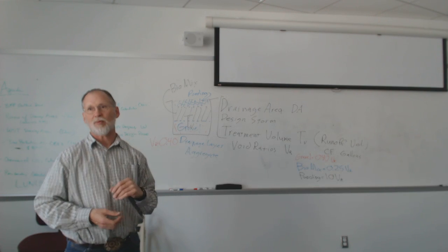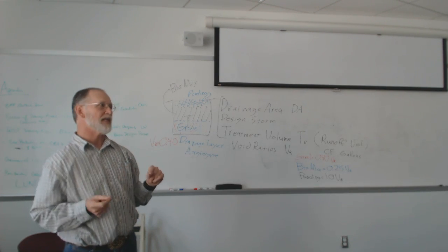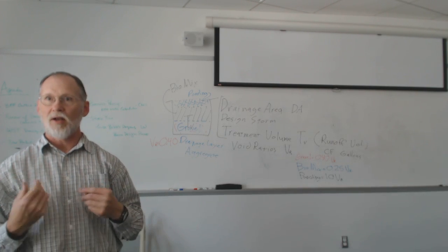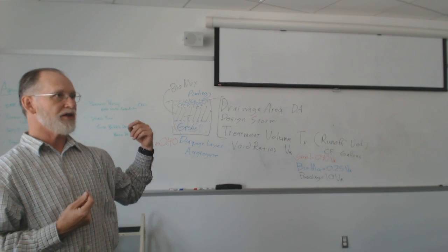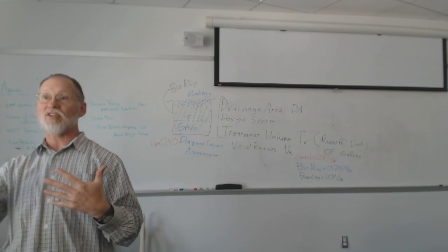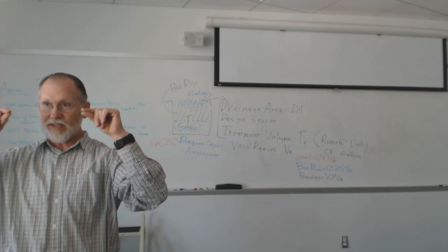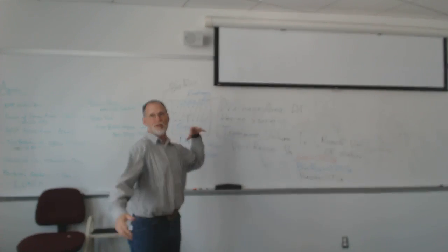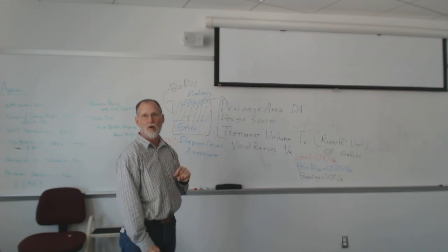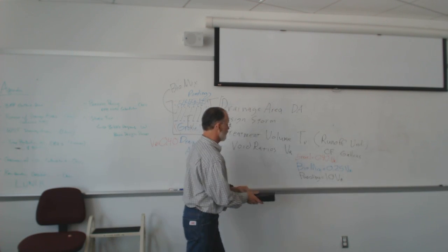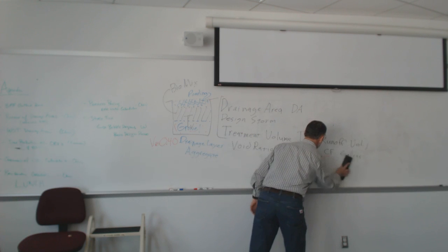These best management practices do very little for those big storms, although when you have thousands of them in an area, it all adds up. But on a given site, when you run the calculations, it always surprises me how little impact they actually have on the 10-year storm. They reduce it a little bit, but it's tiny because they're not designed to capture these huge volumes. They're designed to catch these smaller storms and treat those. So I'm going to move on to rain garden design.